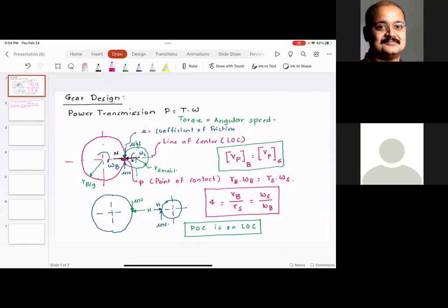Timing belts in the case of Honda, because Honda uses an interference engine. So that goes with the engine design, so that you have a timing belt. But that gives you another problem: if the timing belt fails, then the piston slams on the valve body, and you will have to rebuild the entire engine. So if you have a timing belt, please get it replaced at the manufacturer-recommended intervals.